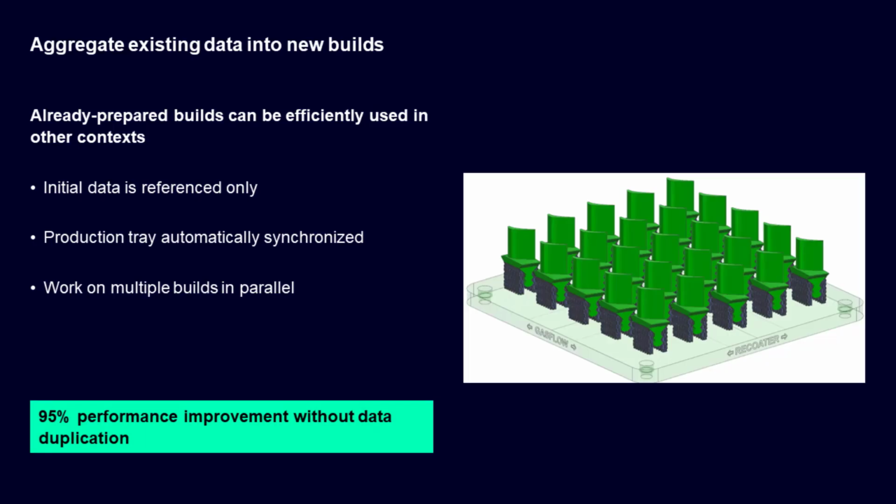When you are working with a build tray that contains a single part, you can add the build tray to another build tray. In the current situation, the build tray with a single part and its supports represents the development build tray. The build tray to which you add a single or multiple copies of the development build tray represents the production build tray. From now on, NX Additive Manufacturing uses part occurrences as associative references from the production build tray to the part data in the development build tray.